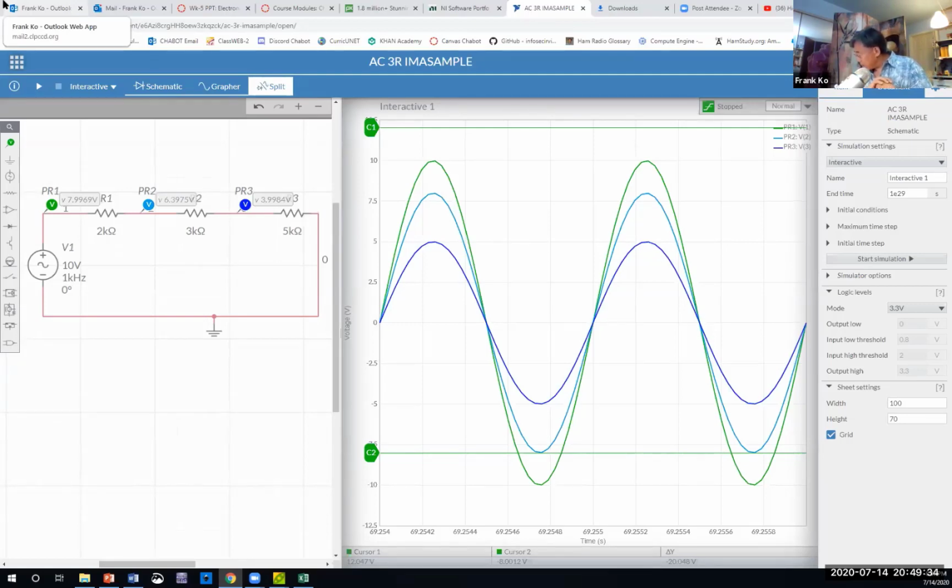No, lamp was 175 watts. You convert 175 watts to 0.175 kilowatts, then multiply by 24 hours, and then you will end up with an answer that's less than 76 cents. It works out to be 75.6 cents.